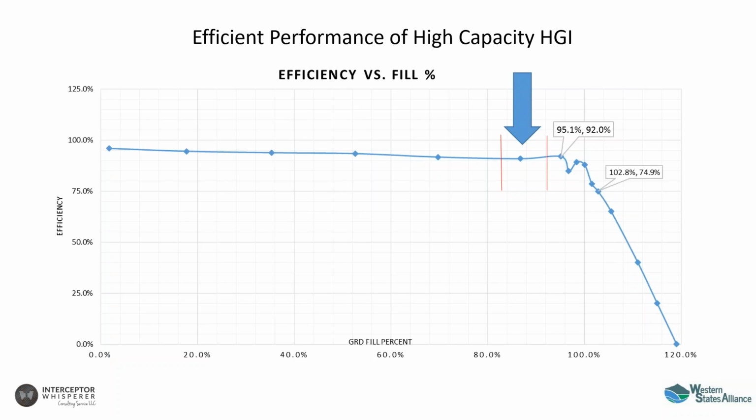So what he did is he went to performance tested hydromechanicals, all of the legacies that were available, because there wasn't any high capacity type available in the late 1990s. They were all legacy style hydromechanical. And when he evaluated the amount of grease at the end of the performance testers at the breakdown point for those devices compared to their liquid capacity, he found that they all fell within a range of 25 to 35% of their total capacity at maximum, meaning they could hold a maximum of 25 to 35% of their total capacity in grease. Hope that makes sense.